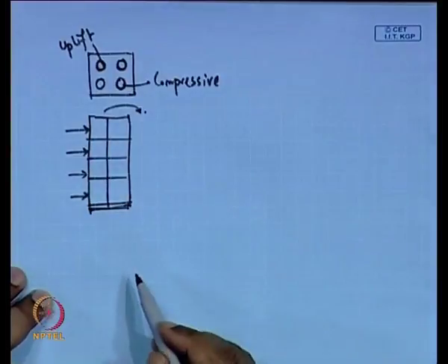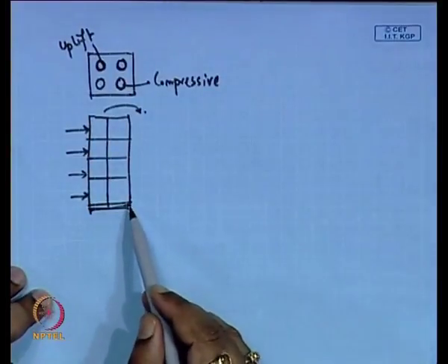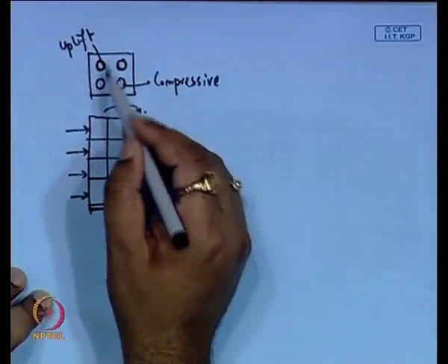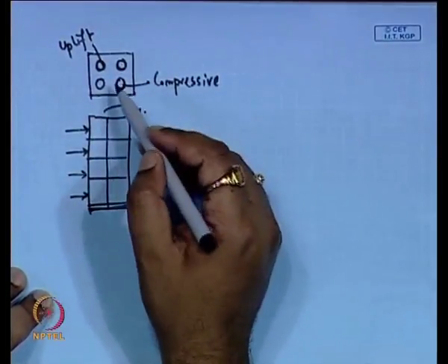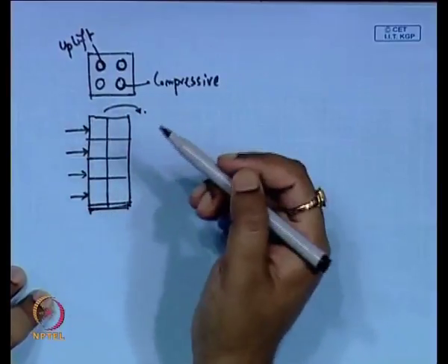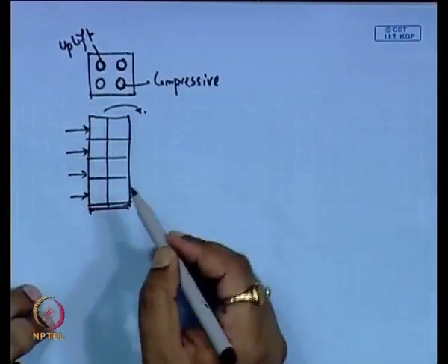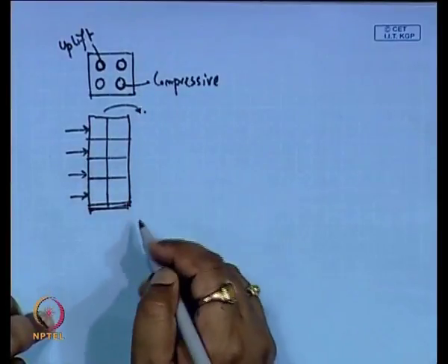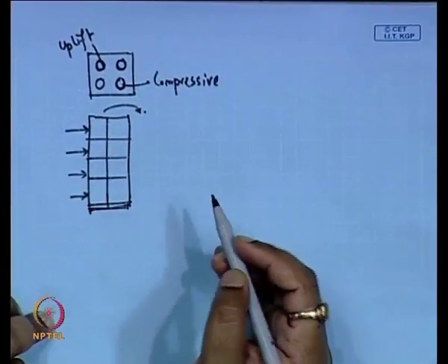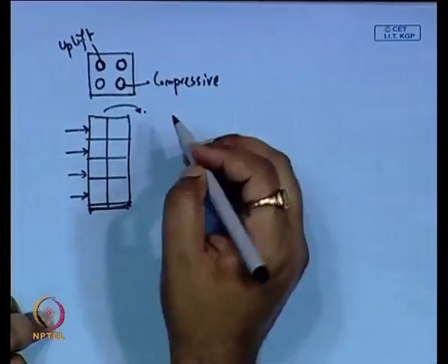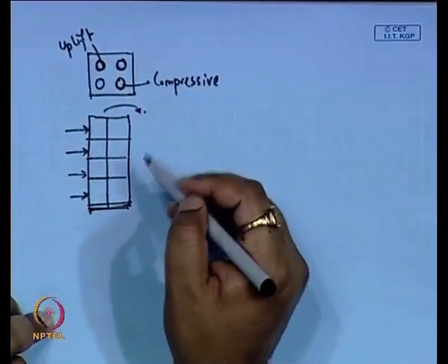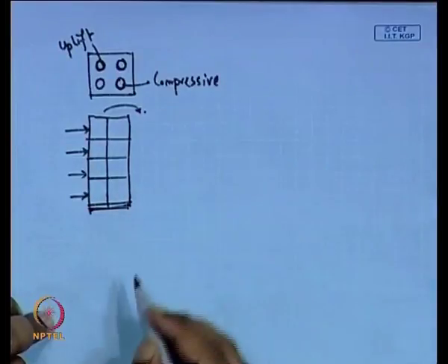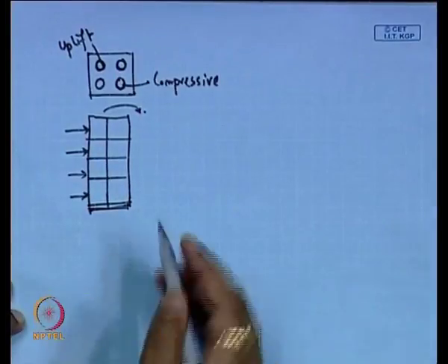A similar case can happen for the pile foundation below a tall chimney, where we also have to design these piles for both compressive load as well as for the uplift load. Now, the direction of this vertical load can be perfectly vertical or it can be inclined also, depending upon the type of structure or the type of loading that is acting, that is, inclined compressive load or inclined tension load. So, this is the vertical load.